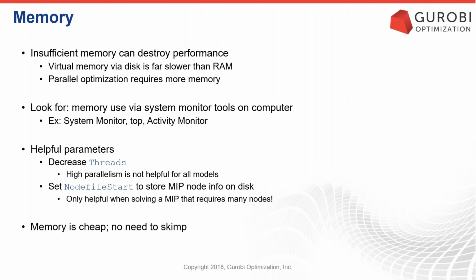During this process, and especially during development, you should really use system monitoring tools to take a look at how much memory is actually used. For each operating system, there is a tool for it. On Windows, there is, for example, the task manager. On Linux, there is the top command. This gives you a good idea of how many resources are needed to solve the model. And if you run short on memory, you can do something about it.